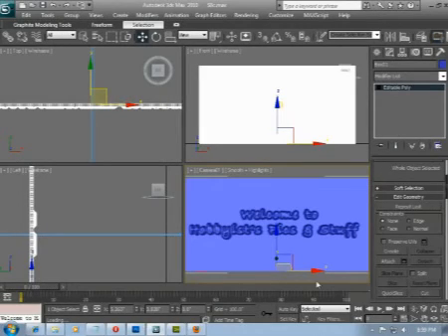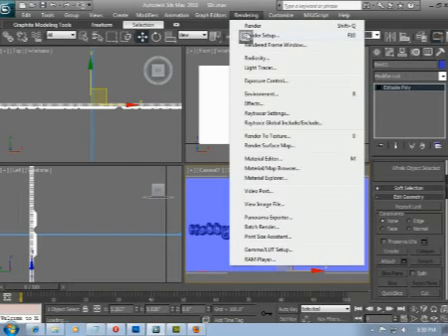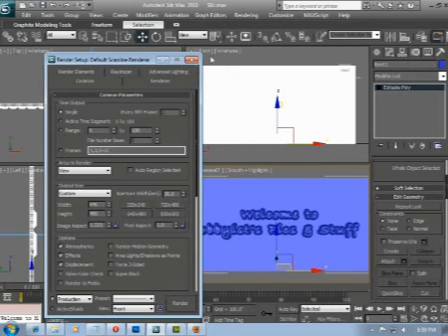Before we can set up the skin in the material editor, we need to lock down what size the output is going to be. I found about 100 pixels per inch seems to work all right. So we modeled the box face at 8 inches by 4 inches, so about 800 by 400 pixels should be about right for the output size. Let's lock that down right now by going to the Render menu and picking Render Setup. On the Common tab, we've got output size here. There's output width, set that to 800, and output height, that's 400.